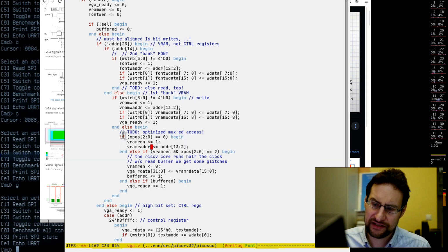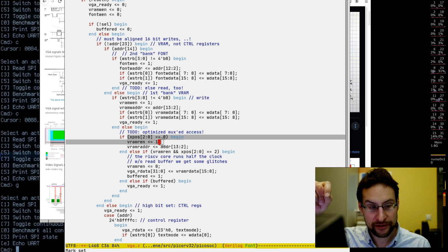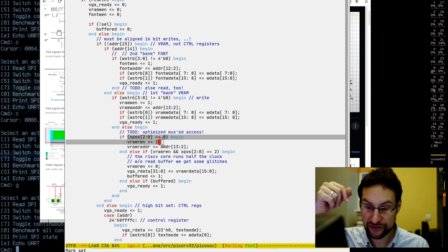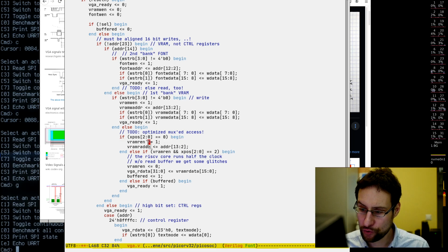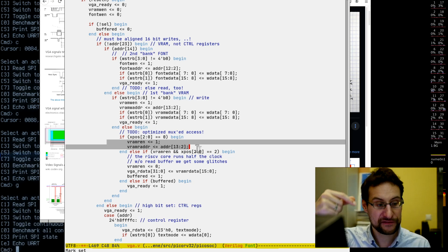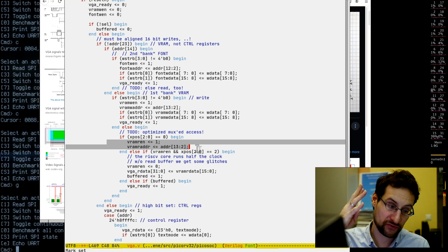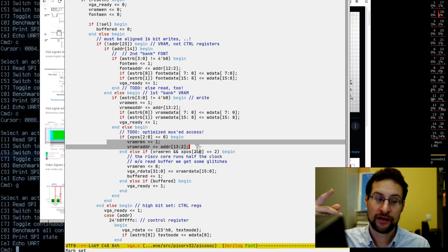The way this works is this code here. I have to optimize more; I'm not really sure if we can optimize more, most likely not. As you see, the higher bits of the pixel address are active in the video output. So we check here for 0. We only start reading at pixel clock timing X position 0 of all 8 bits. So if the video output is active, the RISC-V CPU will be delayed quite some, well, it's not so many, it's only like 2, because it's 4 pixel clock cycles, but it's double data rate. So this is only half the regular clock: 4 pixel clocks, 2 regular system clocks. So potentially idling here, waiting 2 real clocks to have free access to the VRAM.